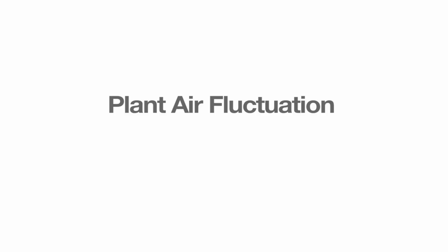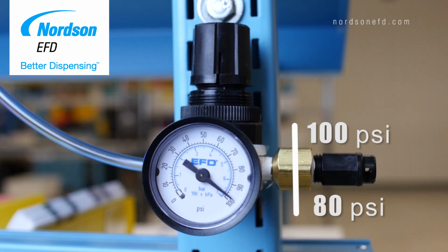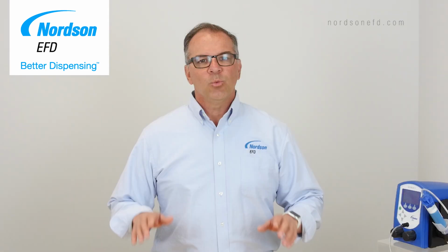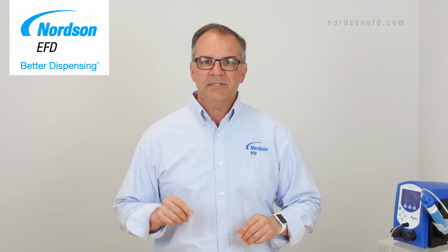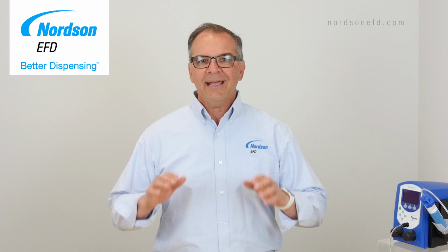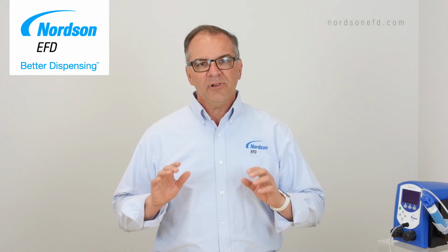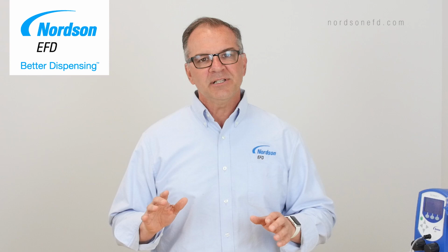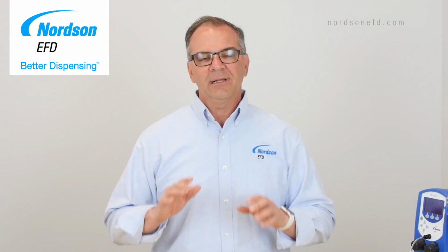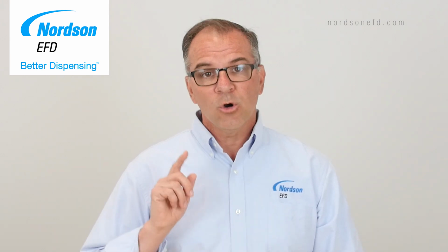In order for your dispenser to work at its best, you need the incoming air to be between 80 to 100 psi. In most companies, one large compressor feeds the entire production floor. When you have multiple pieces of equipment running at the same time, that can create massive air fluctuation. In most cases, the air fluctuates between 20 to 30 psi at every workstation. When this happens, your volume and size of the dispense amount will vary greatly, creating a lot of rejects and a lot of rework. And no one likes rework or rejects.